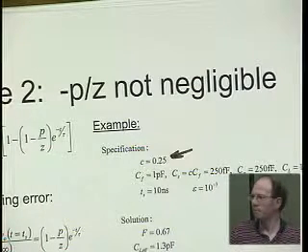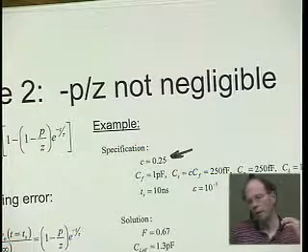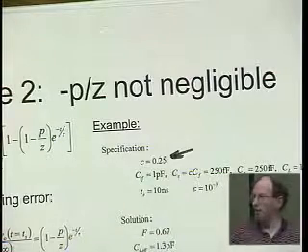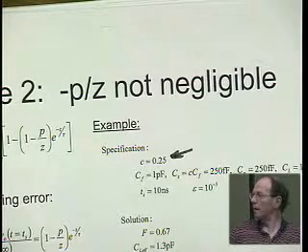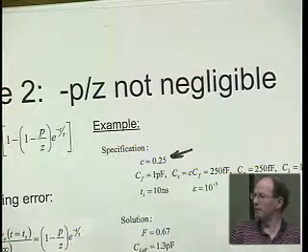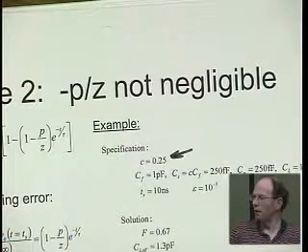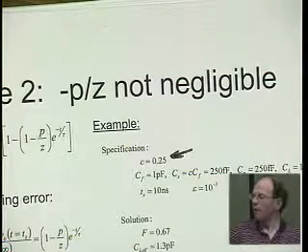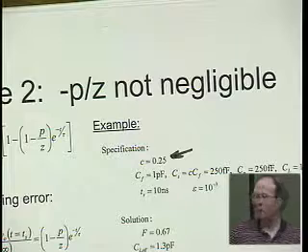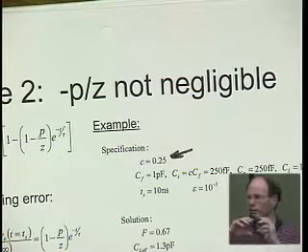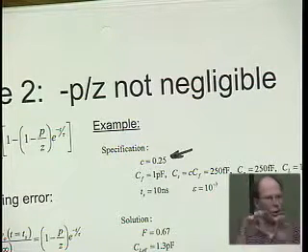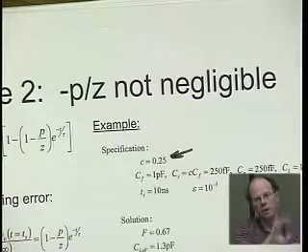But these switch capacitor circuits we're going to see later can also be used for signal processing, in particular filtering. Switch capacitor filters, and there are plenty of cases where, how do we build a filter? Well, we pump our signal through all sorts of switch capacitor stages, one after the other.